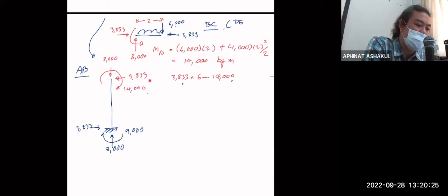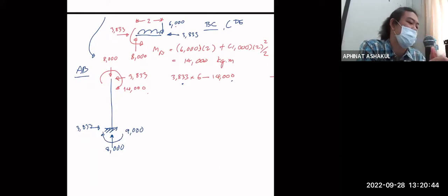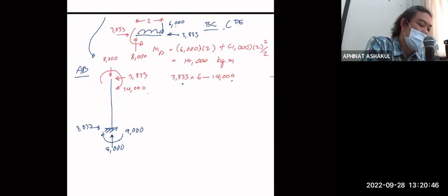But then this one is trying to move your structure to the left. And when this term is greater than that, the end result is that your structure will be moved to the left by this horizontal load. So that's why we need the clockwise moment to counteract that movement, because the horizontal load pushing member AB to the left will generate a counterclockwise moment around point A.